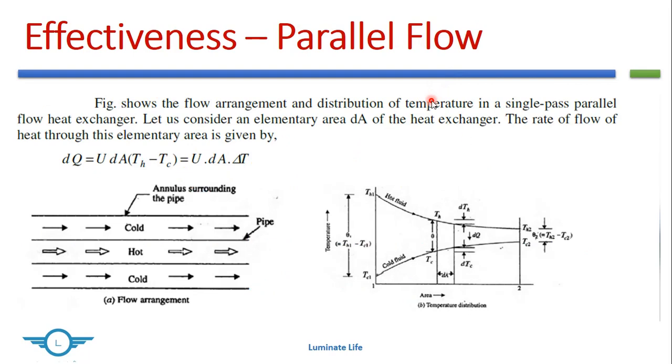Now the first half of the derivation follows the same procedure as the LMTD method, but we will discuss that here. So here the figure shows a parallel flow heat exchanger. Okay. So these are the same criteria. We are taking a small elemental area, there is some temperature drop, so we are going to discuss the heat transfer in the direction of fluid flow.